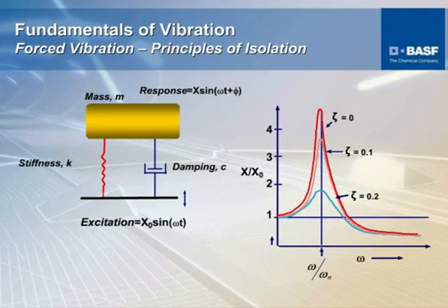The damping concept itself is very important because it affects the overall structural system. Again, depending on the level of that damping, the actual vibration level, which in this instance is the forced vibration, is depicted in this amplitude angular velocity type plot. Essentially, it shows that with zero damping, you have a very large amplitude, which goes to infinity. As you increase the damping, that amplitude goes to zero. Basically, it's very important to have a damping factor and to configure that damping factor so you can reduce the energy or the excitational response of the system to a certain exciting energy.